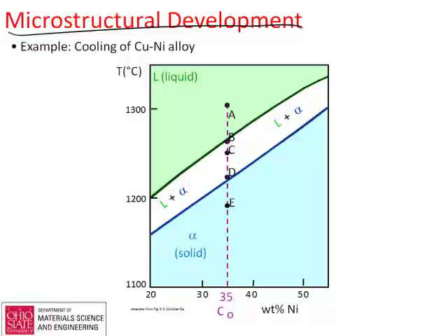That's a mixture of water and some alcohol. The water tends to solidify first, pushing out the stuff that doesn't want to freeze, and you get very similar things with copper-nickel alloy. If you cool down, you first solidify something that is nickel-rich, and you're going to have this is your solid, this is your liquid, and you're going to end up rejecting the copper out.